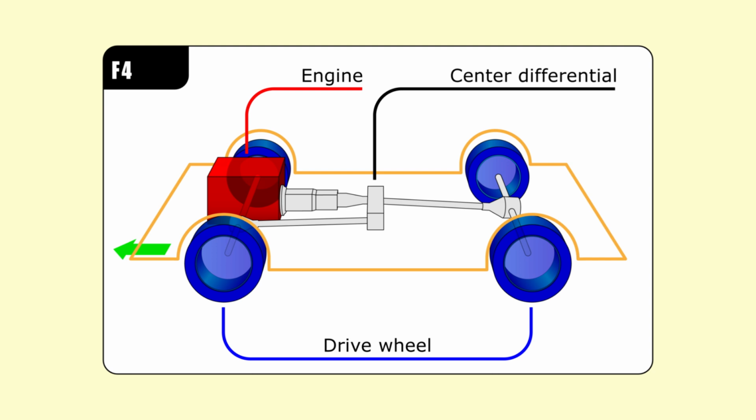Another highly understeer-prone layout is front engine 4-wheel drive. This is due to 2 reasons. One, whilst a portion of the torque has been transferred to the rear wheels, there is still torque acting on the front wheels, particularly if it is a front biased all-wheel drive system like a Haldex. Combined with the discussion we had in the FF segment, this will induce understeer due to the front wheels' dual duties of managing power, torque and steering.